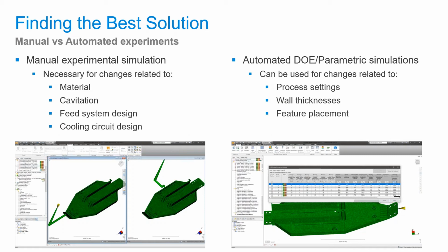The first option is to copy the study and make manual modifications to it, being mindful not to make too many changes so you are still comparing apples to apples, as mentioned. This option is ideal if you already know a direction that you want to take resolving it, or there may be restrictions with including it in the other option, the automated experiment that I'll discuss shortly.